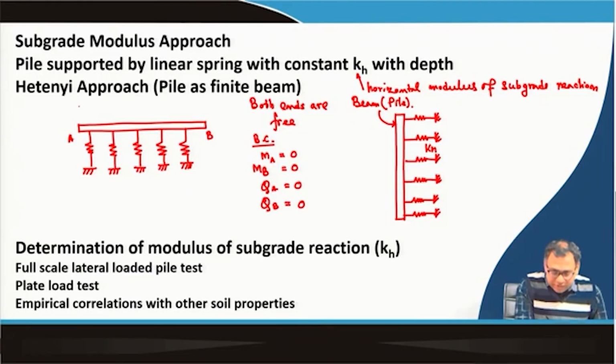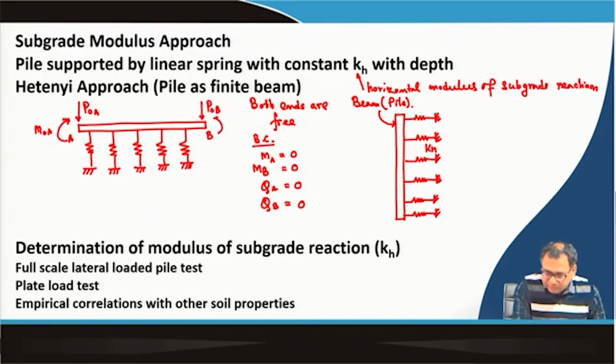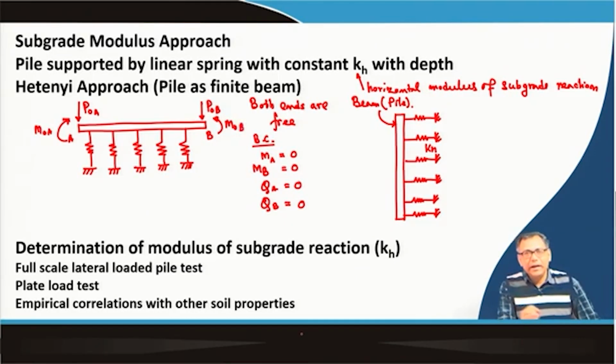Okay. So, that is why these end conditioning forces P0A and M0A we have to apply to make the net bending moment and shear force zero. Okay, that is the concept.